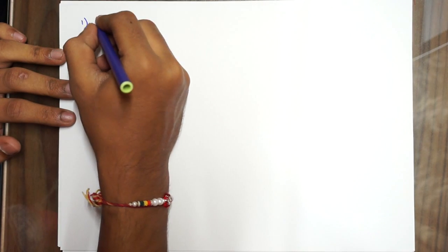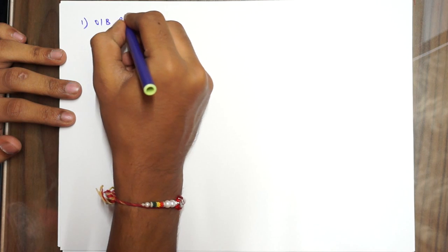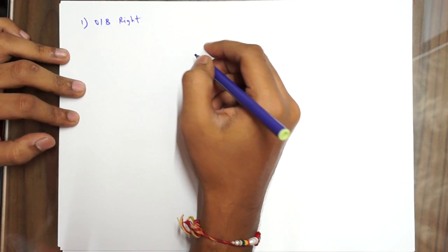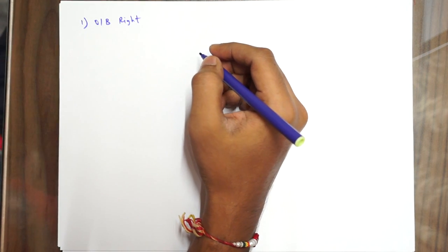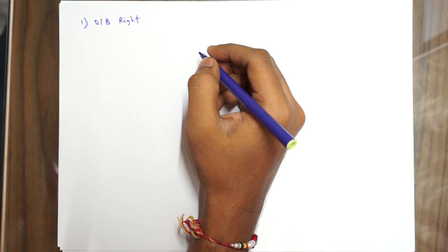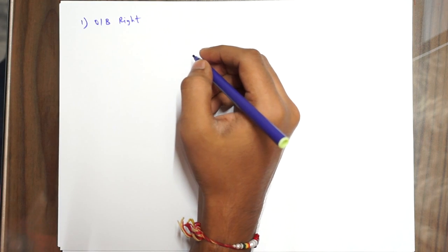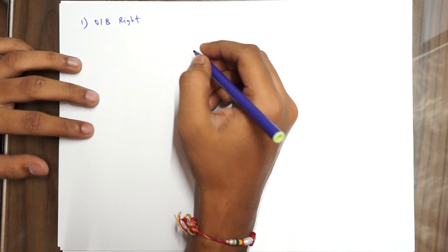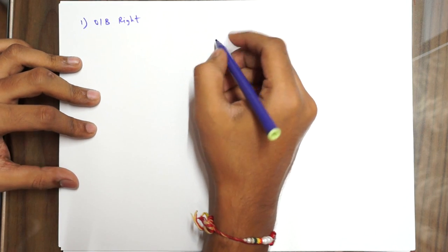Alright, so let's do the first one without wasting a lot of time. Outbound right. Outbound is generally used after takeoff, in case ATC has told you to maintain an outbound DME arc so that you can reach a certain waypoint and then go to your destination from there.